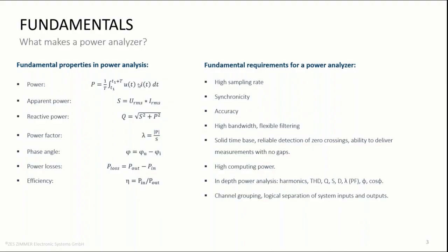The best practice in order to come to the best possible synchronicity is to use internal shunts and channels of voltage and current that are integrated into the same power measurement module. This differentiates power analyzers from other instruments that, for example, only have voltage signal inputs and rely on external sensors for the measurement of current.